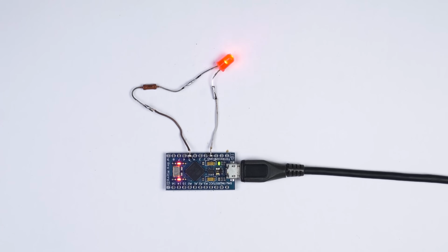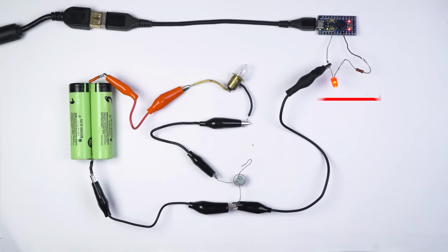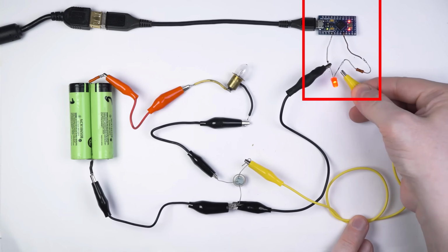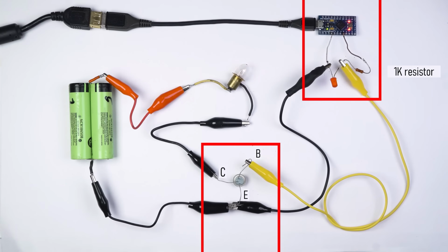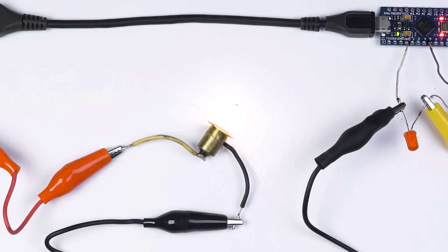This is an Arduino LED flasher. As Atmega's outputs can sink 40 mA max, you pretty much cannot wire to it anything except a regular LED. But you can use a transistor switch to amplify its signal. As you can see, now we are flashing a light bulb. And if you install a more powerful transistor here, you can drive an even more powerful load accordingly.